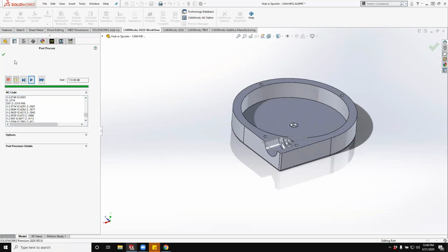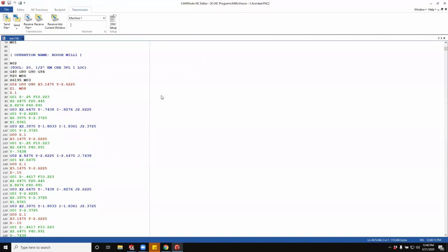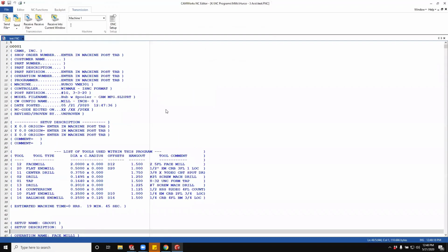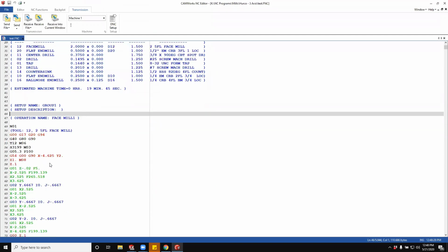That's our 3-axis code. And if we go in our options and say, hey, we want to open that code up in the CamWorks or SOLIDWORKS CAM NC editor, hit the check button, there's our code. And Brian makes a beautiful post. He's got all of this stuff very thoughtfully in parentheses, so we could either read it on the machine control, set width so we can print it on our printer, and then the SOLIDWORKS CAM or CamWorks NC editor shows you what are the rapid moves, what are the feed moves, what are arcs, what are line moves, and what are preparatory statements with the different colors.